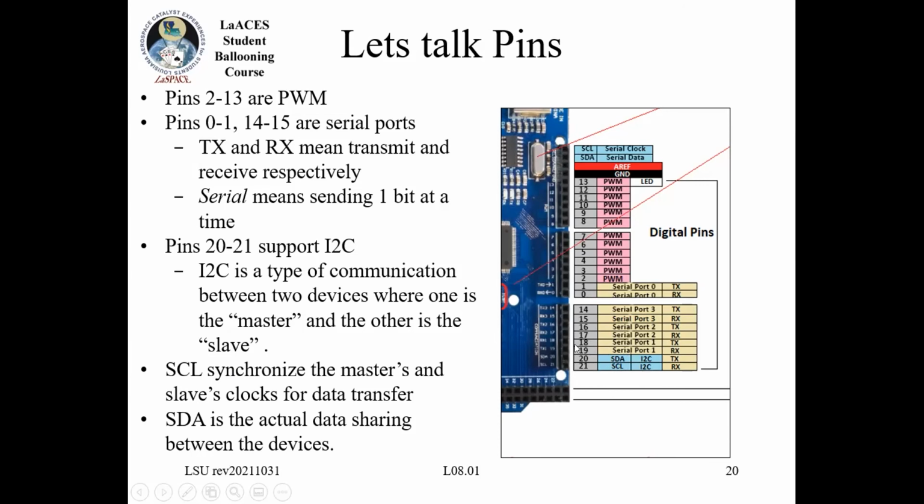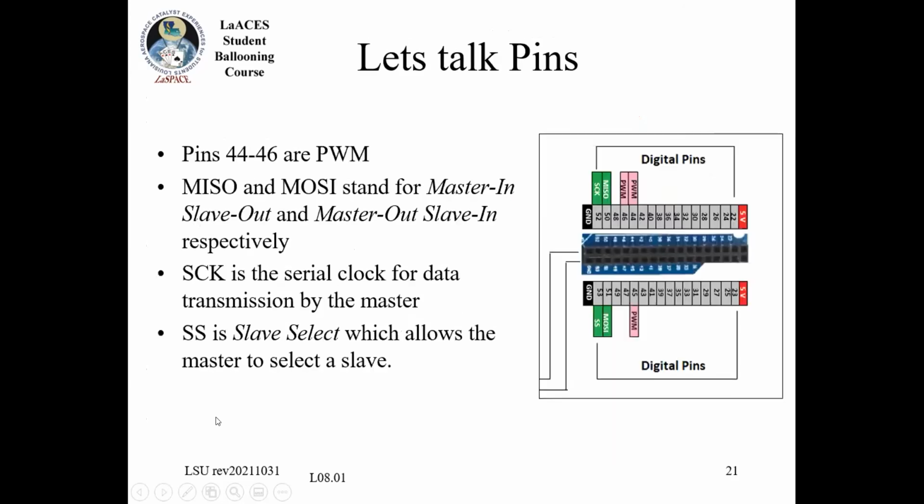In particular, that protocol uses what's called a master and slave protocol, i.e. there's one master device that is sending commands and requesting data from all of the slave devices. Like I said, the SCL is a clock pin, and the SDA is the actual data. We'll cover that more in depth when we start talking about serial communication.